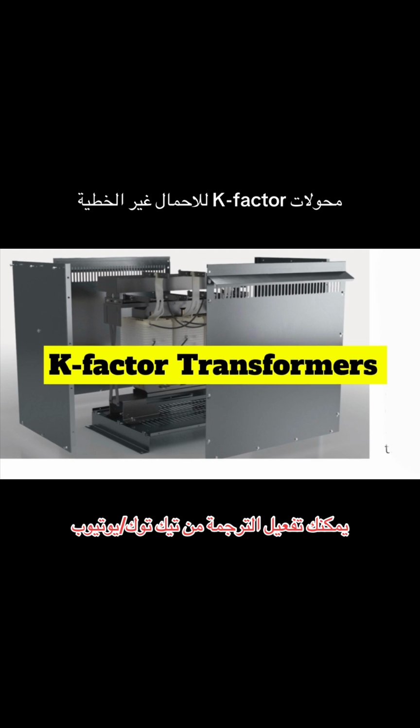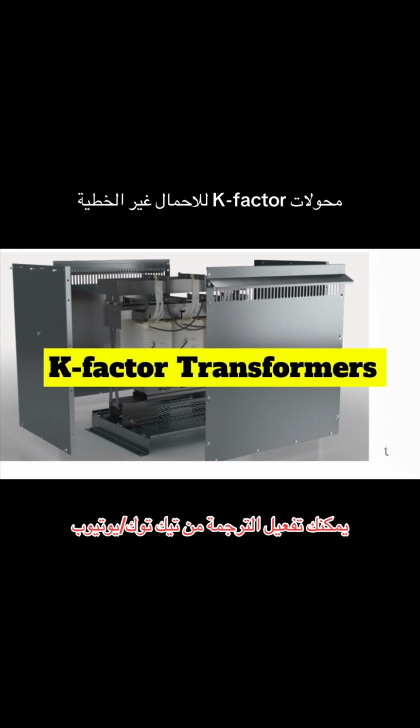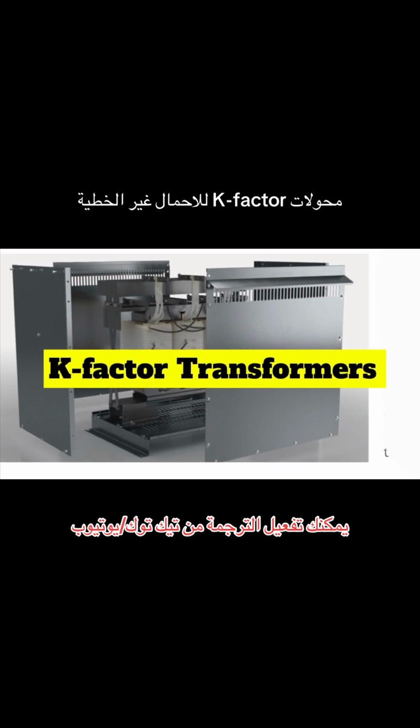Okay, got it. 60 hertz. Now, think of harmonic currents as these extra little ripples or vibrations riding on top of that main 60 hertz wave. The thing is, they're not random. They happen at very specific multiples of that 60 hertz. So you get a second harmonic at 120 hertz, the third one at 180 hertz, and so on. It's a whole series of echoes of the main frequency.